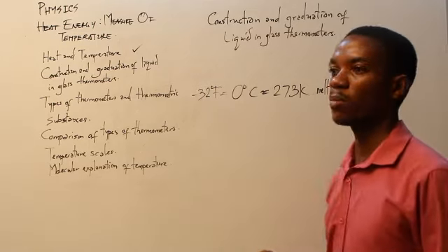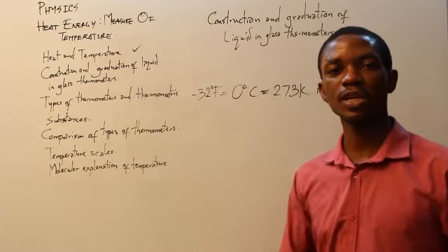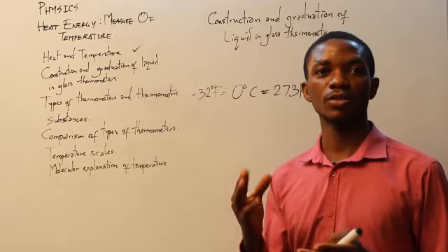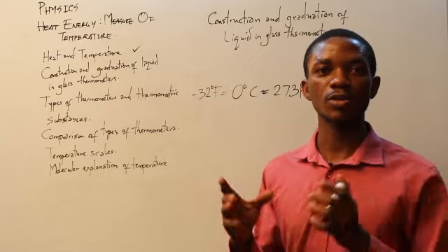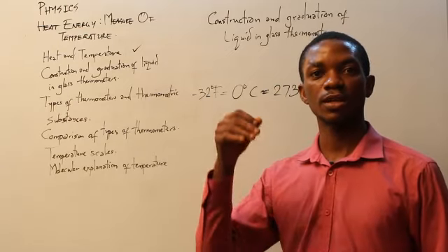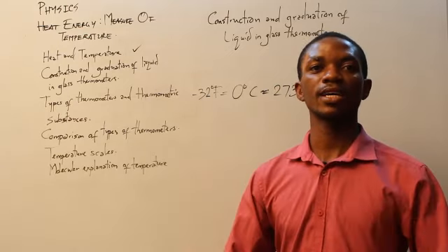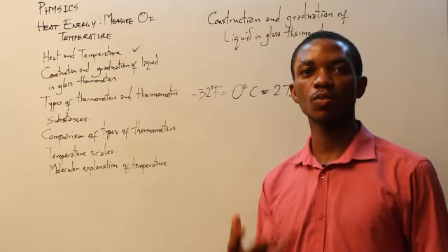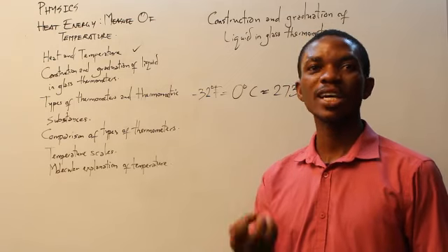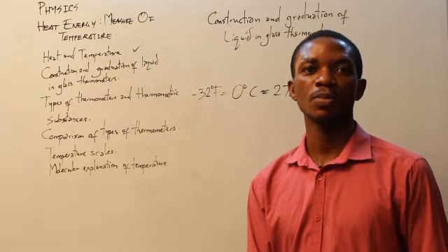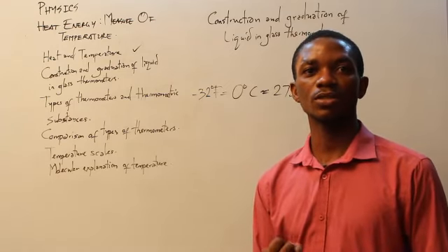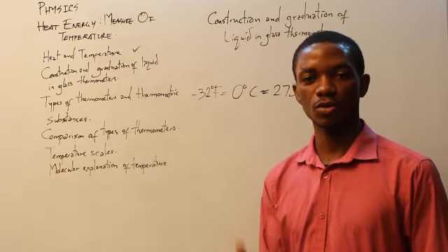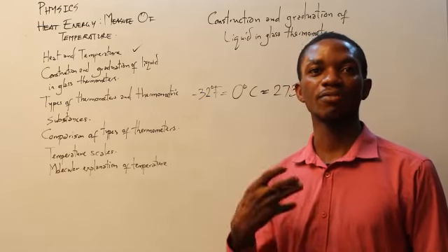To take this particular measurement, after the liquid has been put in the glass, an ice setup, as you're seeing on your screen right now, will be done. You put some ice inside a funnel, and why we're using the funnel is so that whatever water is coming out can drain out of the system, instead of the water beginning to alter the temperature of the system. So the water drains out, we only have the ice.